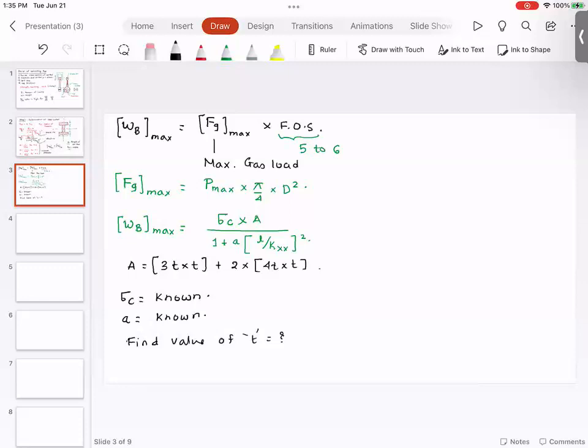And then, for the entire engine or entire component, you trace the reliability. You take the reliability of the connecting rod, the bearing, and all other components, and at the end you have a mathematical equation that tells you how long this engine would perform without any failure.